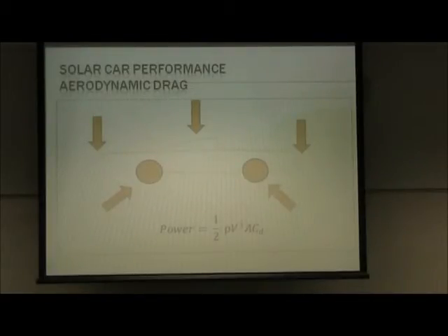And you can test for that going down the street. If you have a little bit of smoke coming down or dust coming out of it, you can see the actual eddies. There's two types. There's the type that curls in because you don't have a knife edge, and then at the corners, sometimes you see vortices. There are vortex elimination things that people sometimes will put at the corners to try to prevent that from happening. Stanford had those on the top of their car. But you want to test it, because if you're not testing it, you might put on something that actually makes it worse. It's tough to do without testing.